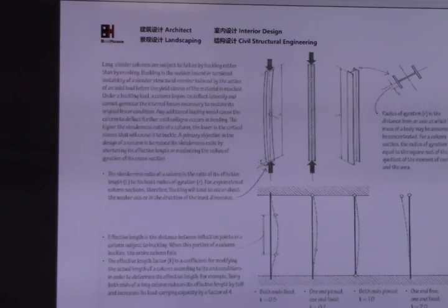That's why, for example, when we see a light column, a straight light column, it has a very big base here. The base is for the bolts, right? If we only have two bolts, it is a pin connection. It doesn't work, because that post has a moment, right? So usually you see four bolts. Four bolts is a moment connection, so it can resist the moment.